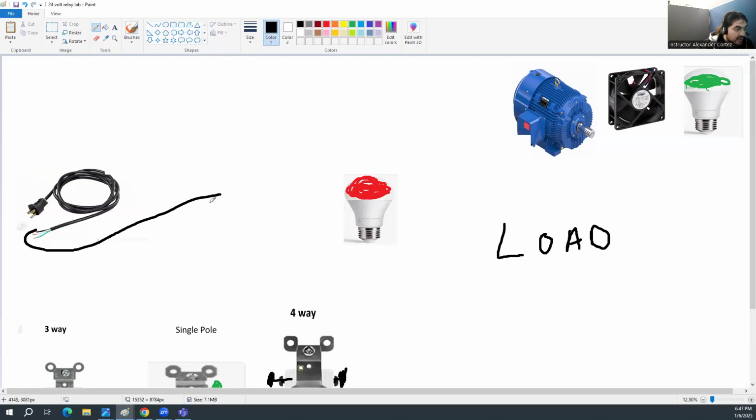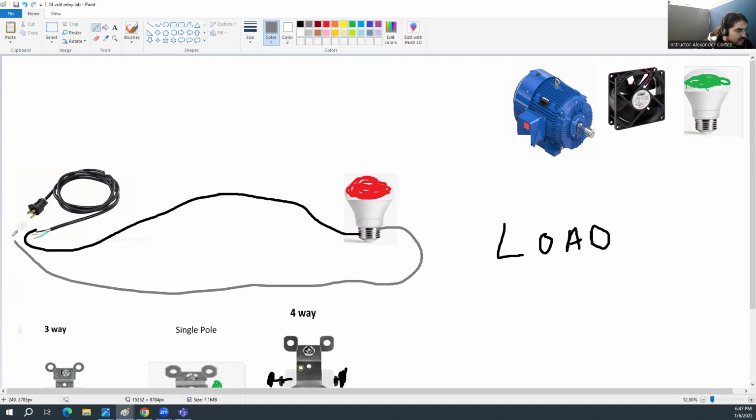If you connect that black wire to the brass terminal on a light base, and you plug this in with just the hot wire connected to your light, electricity won't flow, because it needs a closed loop, like I mentioned earlier. That means we need the neutral to come back to source, back where it came from.